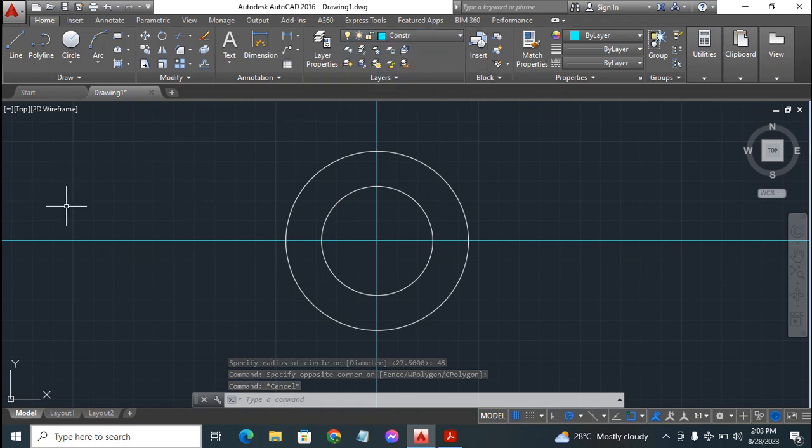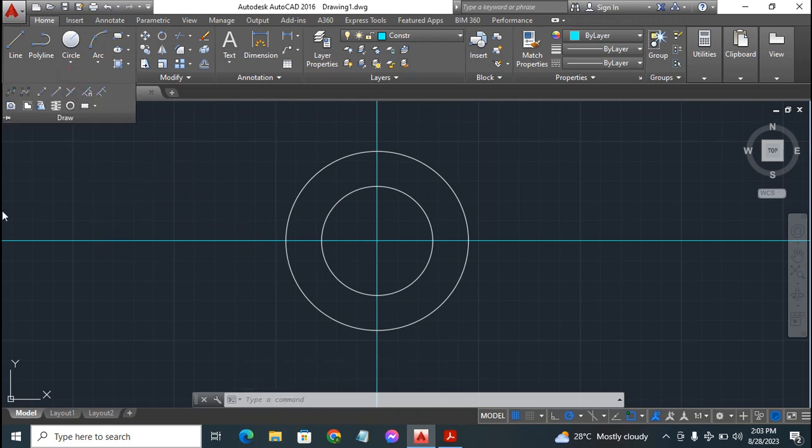since we want to put in construction lines. Once you've done that, you go straight to the drawing board, click on the drop down of drawing board, then you click on construction line where my cursor is right now. Click on it by left clicking on the mouse. Once you've done that, you type in A for angular in the command line to tell CAD you want to put in an angular construction line, and press enter on the keyboard.